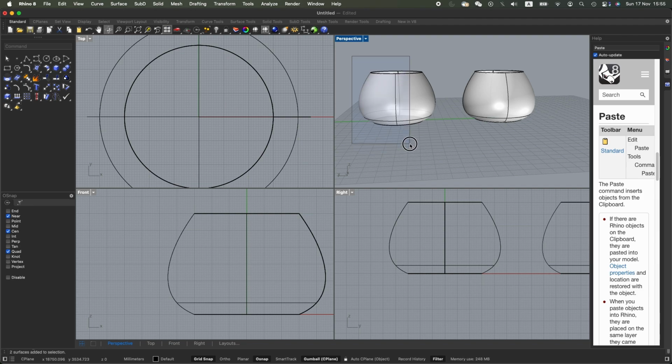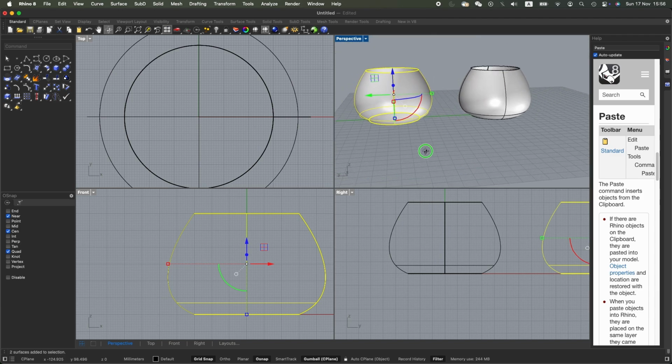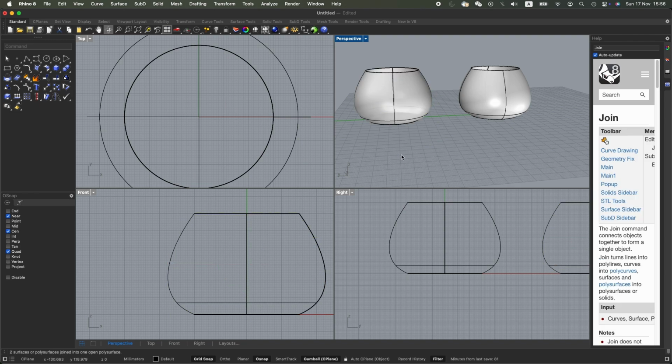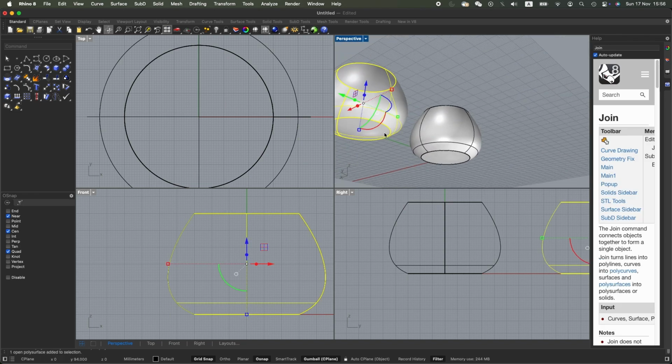For example, in this way you need to cover the whole shape. If you don't cover the whole shape, it's not going to select anything. But in the other direction, you don't need to select the whole shape. You can just touch the shapes that you want to select. So now I'm going to type join, enter, and this is my final shape.